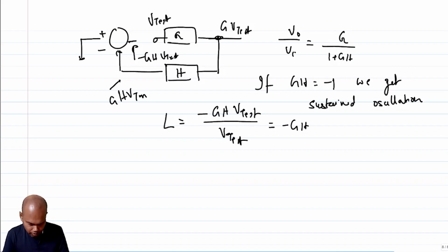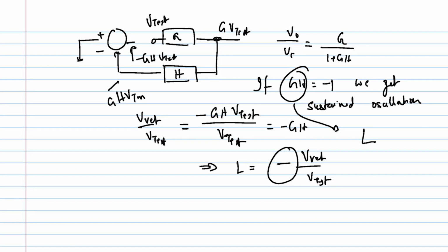Okay. So can we show our LC oscillator with cross couple pair satisfies this condition? Let's see if we can show. We do not have to bother about that LC part, because all we are interested in is to see if we can take the loop gain to cancel out, if we are getting the sustained oscillation condition under the condition that I have only R and the Gm, right? Because the LC parallel combination at resonant frequency is going to give me infinite impedance anyhow, right? Okay, so let's do that.